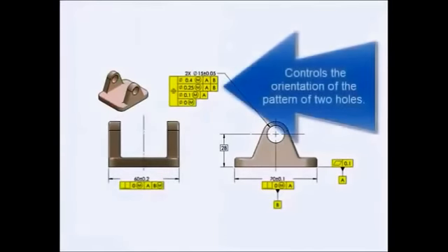The gauge you're about to see is for inspecting the second segment of this composite position tolerance. Since the datum referencing is there only for orienting the pattern, the gauge elements or pins that are going to check the position of 0.25 have to remain parallel to both datum planes, but be free to move around in location, and you'll see how that's accomplished.